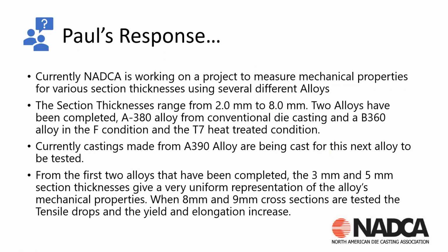First off, NADCA has a project where we are taking castings of various alloys and we're excising test bars from those castings. This is a multi-year project, and currently we have done samples from A380 and B360. With the B360 samples, we checked them in the F condition, or the raw condition, and in the T7 heat-treated condition. The current alloy being checked right now is A390, and these parts are being cast, and then we'll be taking samples from those.